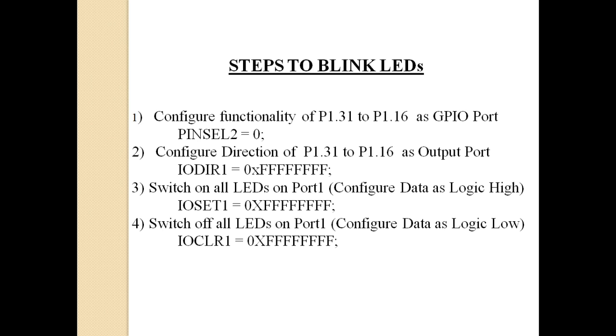Most of the other microcontrollers like Arduino, Atmel, PIC, etc., they are operating on 5 volt VCC, but ARM based microcontrollers will be operating on 3.3 volt VCC, right? So if you want to make the LED on, you need to generate a VCC of 3.3 volt in that pin. So if you want to generate a 3.3 volt VCC there, in digital you need to write a logic 1 there or logic high there.